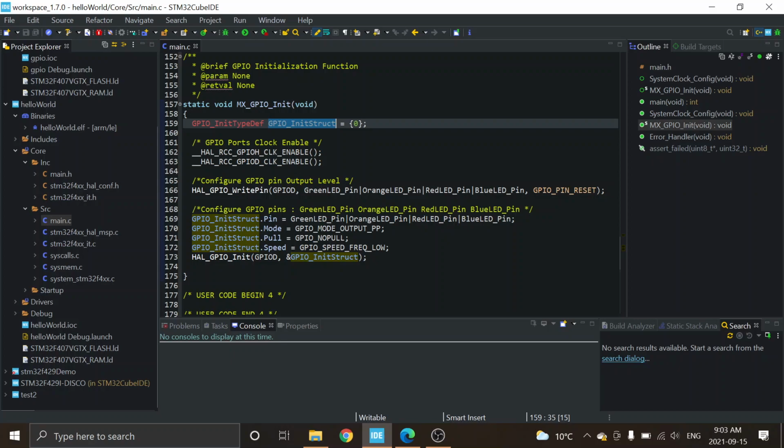Why are the variables inside that structure 32-bit when you said the pins are 16-bit? Great question. We're dealing with a 16-bit port. A lot of registers, not all of them, need more than 1 bit per pin because there are so many different configuration options.